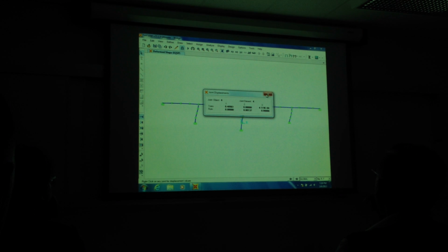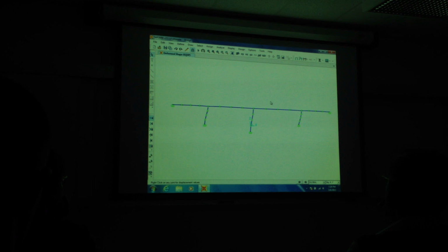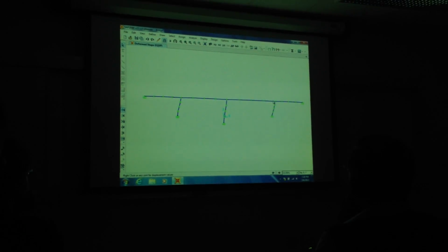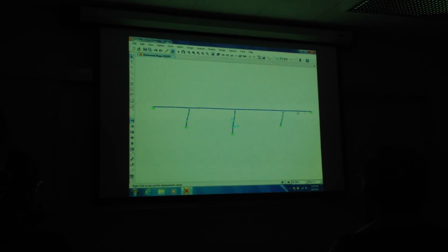And there's a slight variation because of the axial flexibility of the deck, but relative to the flexibility of the columns and bending, the axial stiffness is much stiffer. So I'll right click over here and 0.41. So it's almost the same all the way along the line.